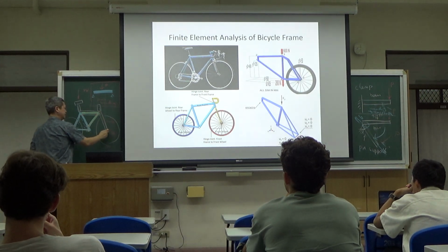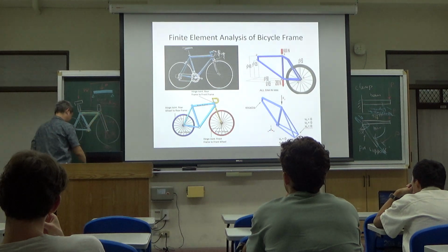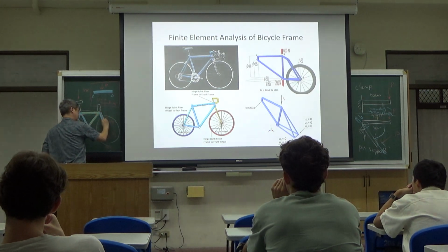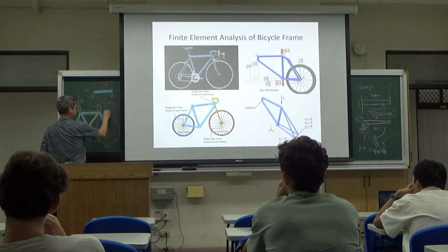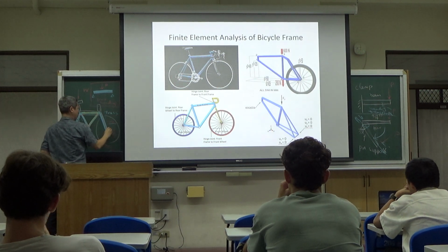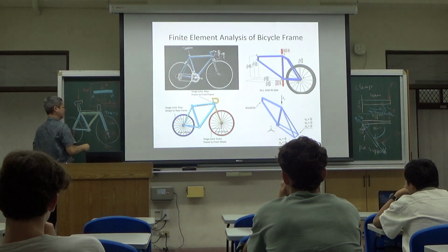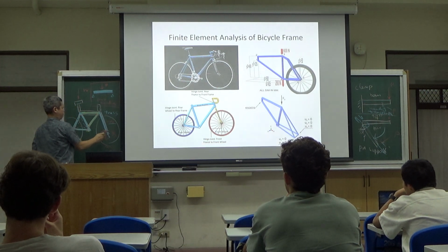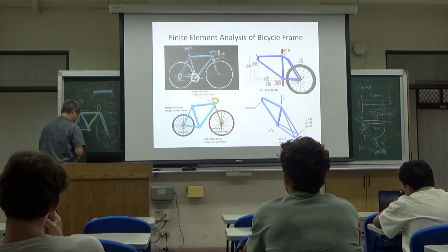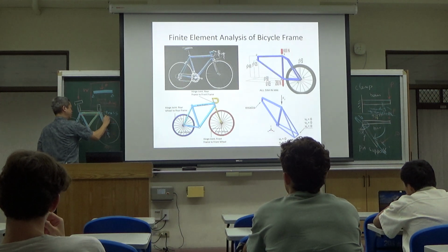In this case, this element is going to be modeled both as a truss because of the axial loading, as well as a beam because of the transverse loading.